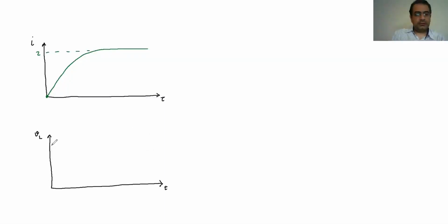So the voltage in the inductor at the very beginning when we close the key is going to be the same as the voltage in the source, and then eventually it just drops all the way to zero. Eventually the voltage in the inductance becomes zero, and that's how it's going to behave as a single wire.